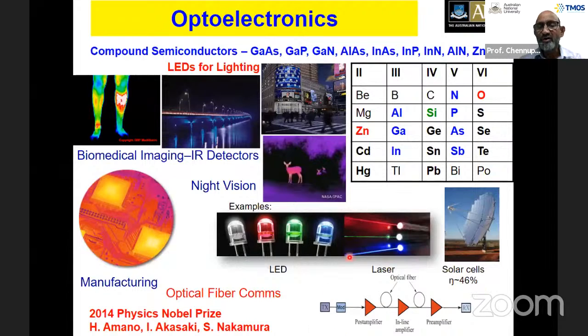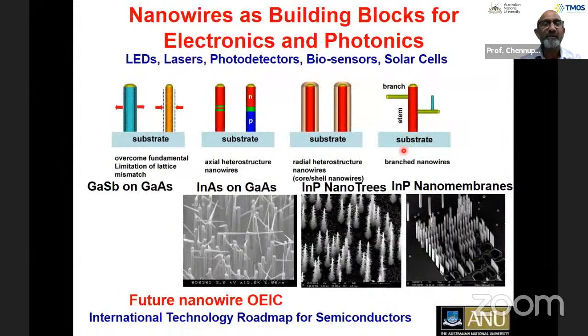Today, I'm able to talk to you because of optical fiber communications, where the electrical signals from my computer are converted into light signals by using lasers, and then they pass through the optical fibers. On the other end, we convert these back into electrical signals by using photodetectors. Again, indium gallium arsenide phosphide materials are used for this purpose because optical fibers are most efficient, in terms of absorption and dispersion losses, in the infrared region of the spectrum, the 1.3 and 1.55 micron window region.